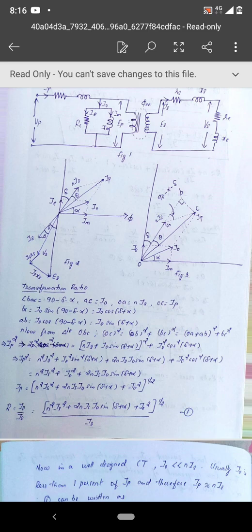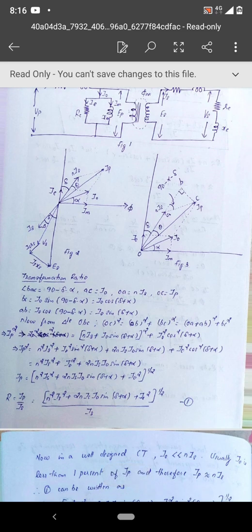So theta, as I told, is the phase angle of the transformer, that is the angle between IP and IS reversed, that is NIS. And delta, as explained, is the angle between the secondary terminal voltage VS and the secondary current IS. And you can understand from yesterday's discussion how you can draw ISRS, and perpendicular to that you draw ISXS. ISRS has the same direction as IS, and VS plus ISRS plus J ISXS will give ES.